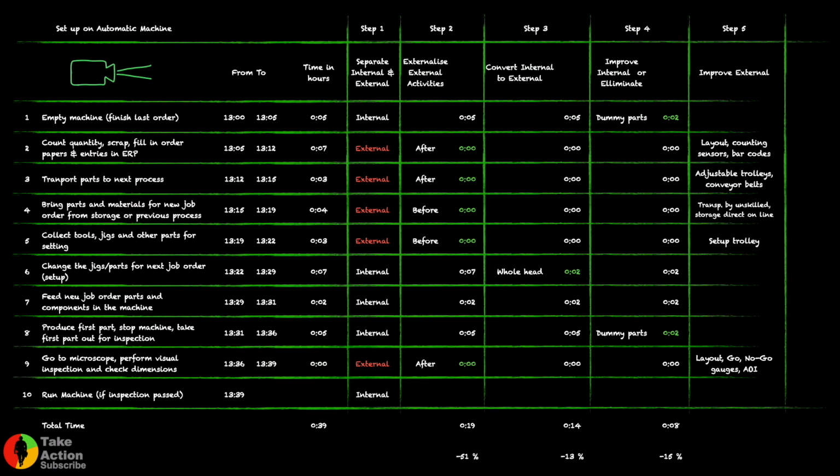Last but not least, we have step number 6, and in this step we aim for completely eliminating the need of setup at all. So in this step we are asking the team members, and research and development also is included here, to go for design changes: if we have 2-3 different articles, can we reduce the number of articles? In our example, we were supplying to a few customers where on the same product only the number of pins were different. Some were having 2 pins, another 5 pins, another 10 pins, and with a simple change in design.